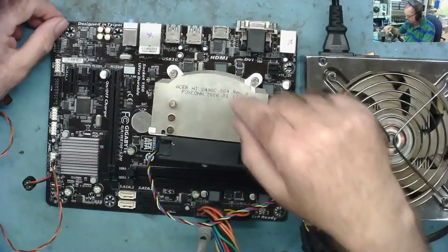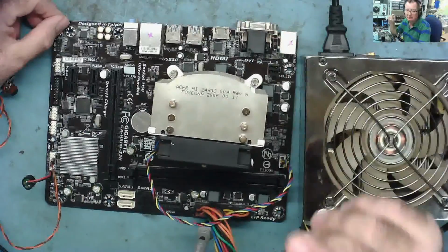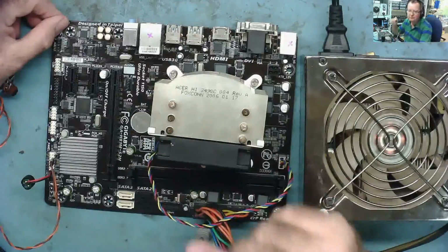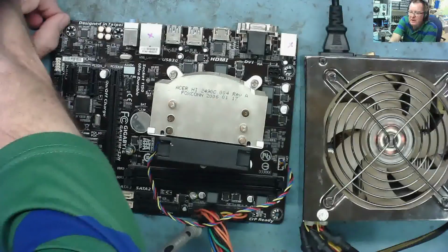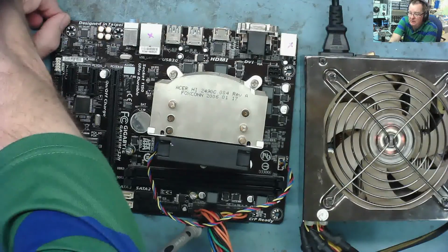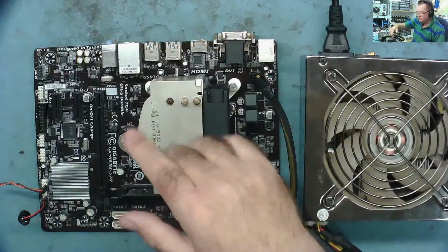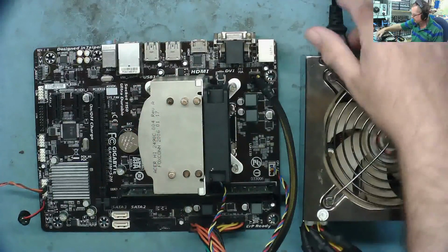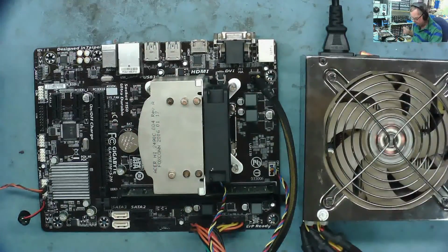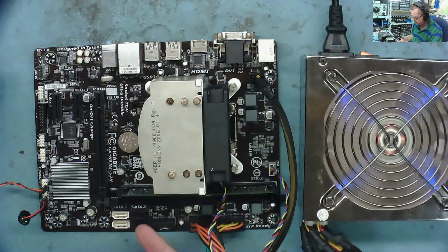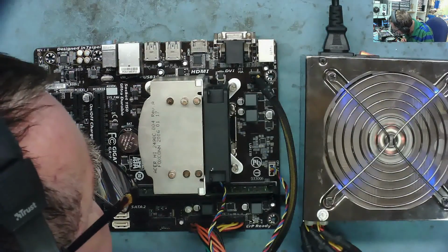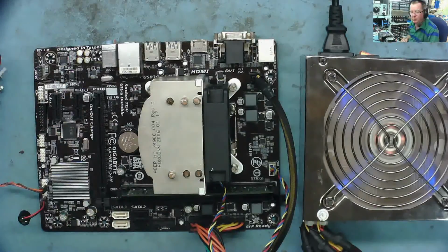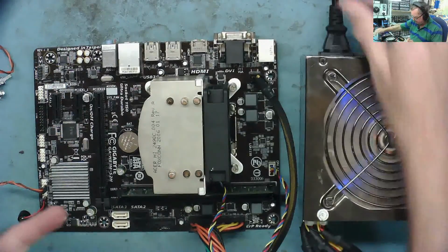To prove that point, and this is without the 12 volts connected as well, let me get the other known good board and we'll see what happens if we force that one to run. It should stay on. Okay, this is the good board. I've put the same CPU on this one. It has RAM in, so this should power up, stay on, and bleep once. I've got no monitor attached, but yeah, I got one bleep there. So that powers on and stays on.